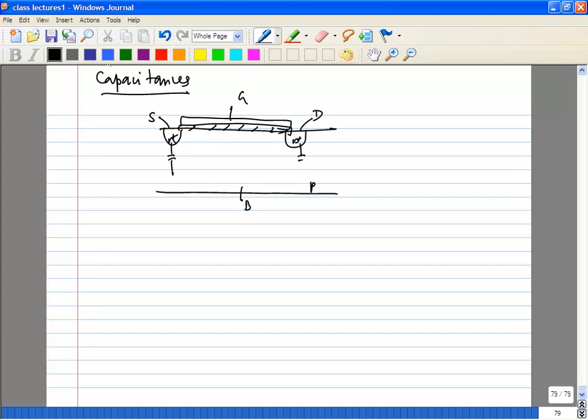Remember that for any MOSFET, your gate doesn't exactly end where the source or drain begins. You have an overlap region LD, and so your actual length is L minus 2 LD. Then you have a gate to source and gate to drain overlap capacitance through the oxide.